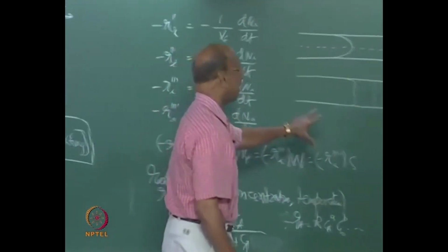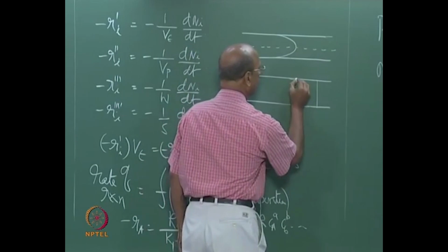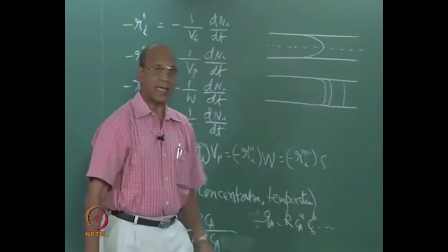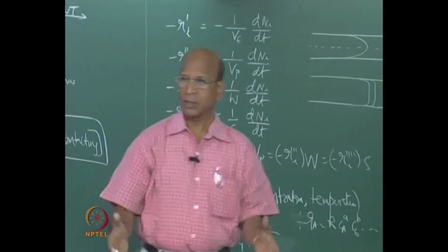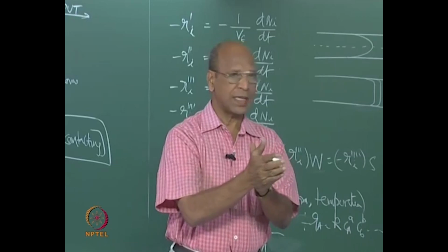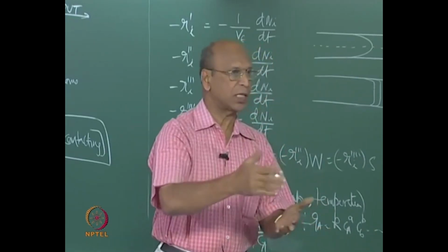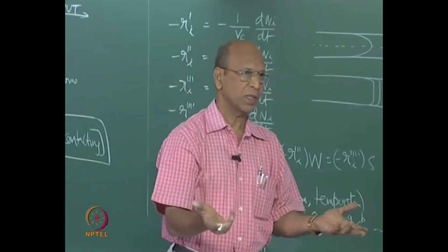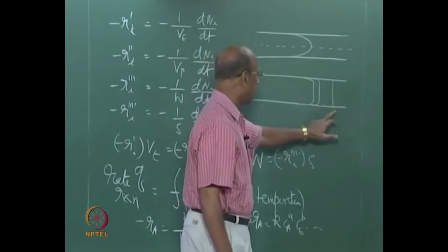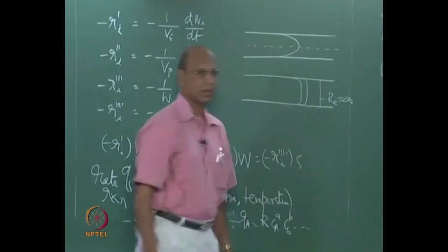Otherwise, whatever Reynolds number you use, maybe 70,000, what will happen? It may be like this. As long as you have the walls, some molecules still cling to the wall, and then you will have zero velocity there. From 0 to flat velocity, there must be some continuity, right? It suddenly cannot jump. That is the reason why, theoretically speaking, Re equals infinity for this profile.